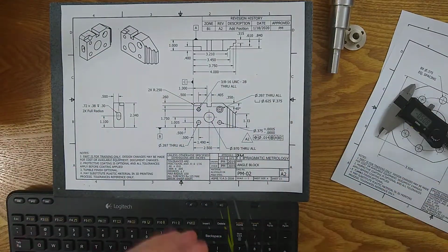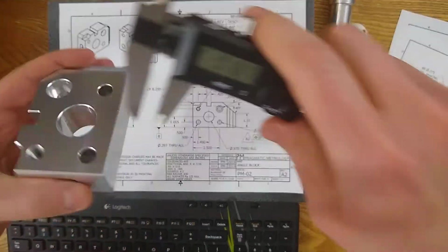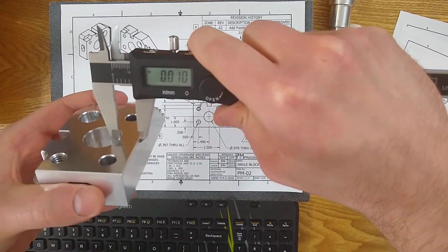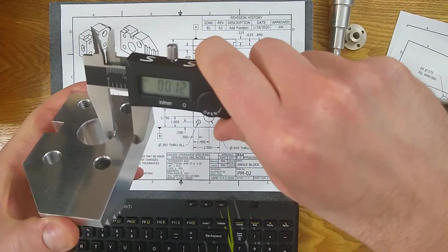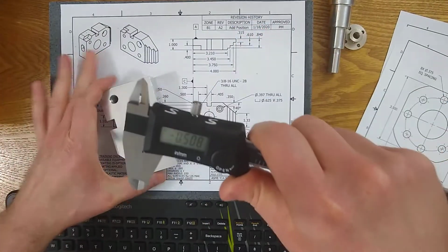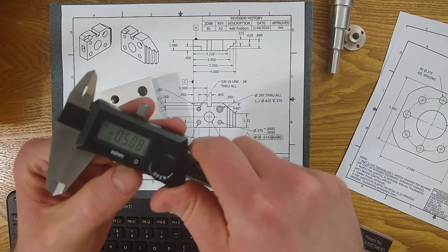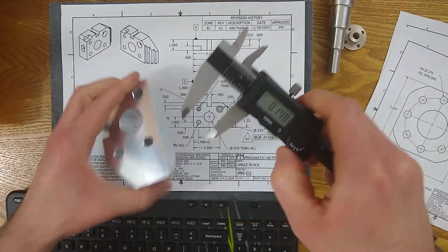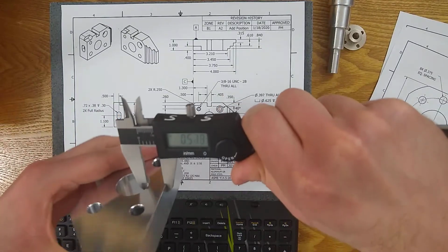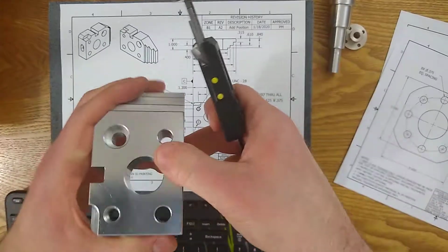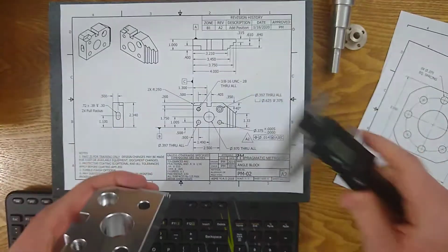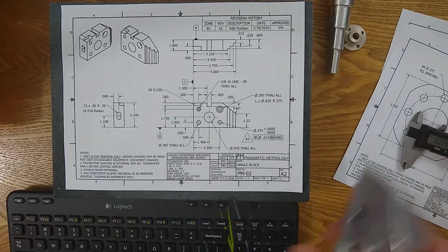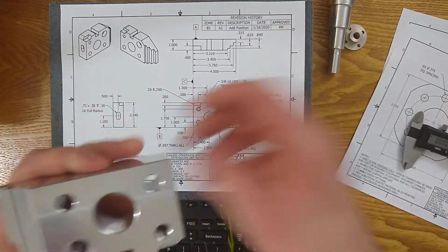There's many other ways you can do it. Surface plate will be a great way to do it. A caliper from the bottom here and then the bottom here will be another great way to do it. Still on 0. A while ago, I zeroed this caliper and I didn't re-zero it. So 519 from that side and 518, 519 from that side. So it's oriented pretty well relative to this datum.